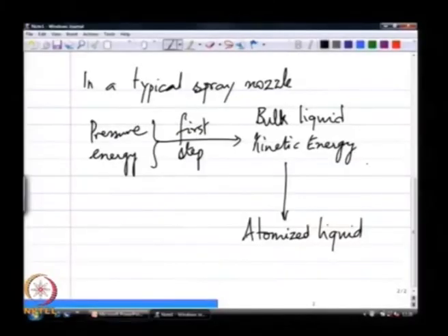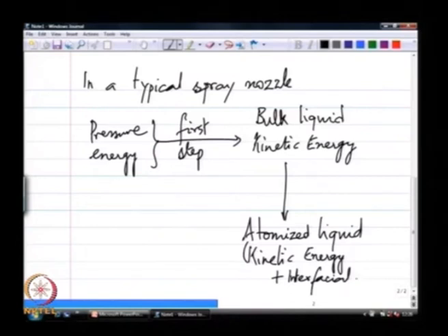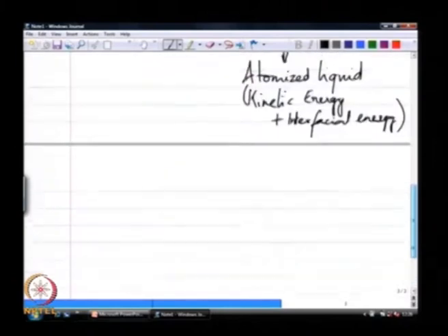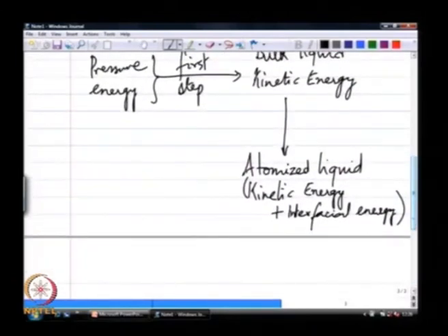Therefore, you are always going to be left with some kinetic energy of these drops plus interfacial energy. So, well, actually I cannot say that it cannot happen at 100% efficiency, although it can. Thermodynamically there is no reason to believe that process cannot be 100% efficient, because this is not a cyclic process, because all of our ideas of second law are only valid for cyclic processes.